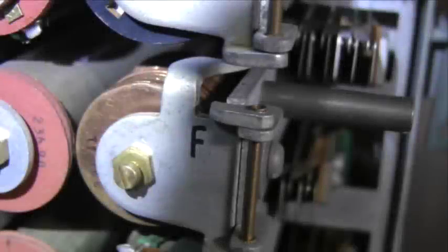Operated contacts 1 and 2 complete the energizing path for the F relay's secondary winding. The stronger magnetic field of the secondary winding causes the relay to fully operate. The operated F relay cuts off the ringing generator from the tip and ring leads, or in telephony terminology, trips the ring. It also bridges together the voice transmission paths of the calling and called stations.